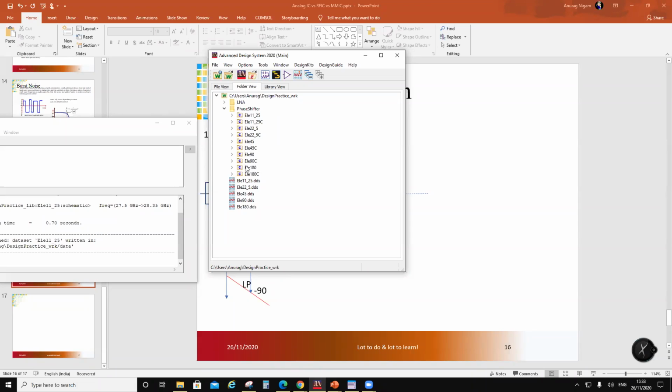Well, this phase array, this 11.25 step, if you want to do much finer steps, let's say 5.625 and even further smaller than that, is this going to result in any accuracy on the whole phase array? And second thing is, how difficult is the calibration of that phase array going to be, right?